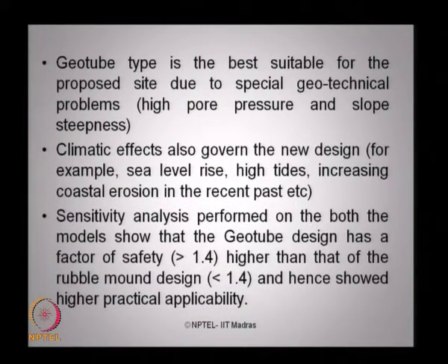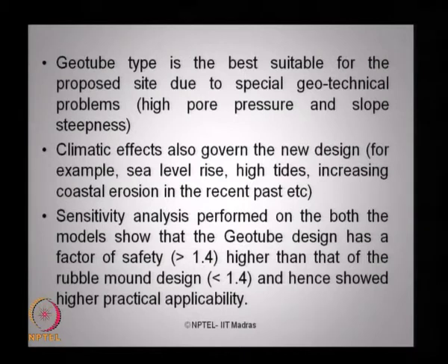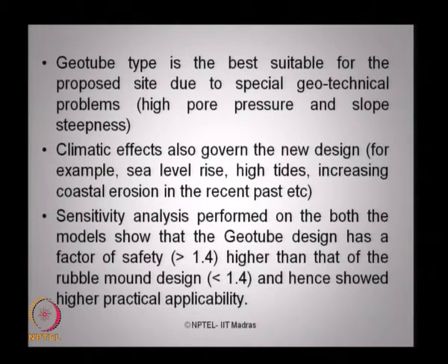Further, importantly, the sensitivity analysis performed on both the designs shows that the geotube has a higher factor of safety, which is much more than 1.4 when compared to that of conventional rubble mound design, and therefore, this shows very high practical applicability of the design.